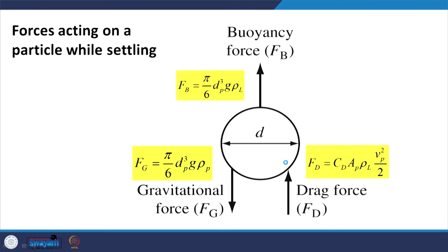In general, sedimentation, what are we talking about? We have a tank. What's the role of the tank? We are providing enough time for our particle which is flowing along with the water. So water is flowing in this way. I'm talking about horizontal flow. So by the time it moves out of my settling zone, the particle should have settled down.